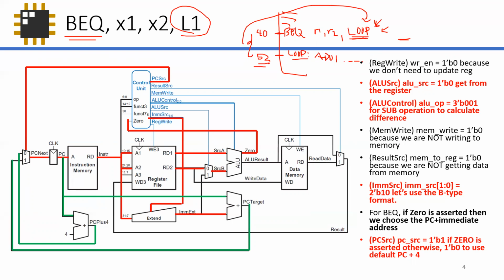So we don't really specify the immediate. But the one you're pertaining to is that, unlike for store word instructions, SW x0, you specify the immediate, 12, and then x0 or whatever register you're trying to put in here. So yes, it is in multiples of 4. Or rather, it's from the software designer's perspective that I have to put it in multiples of 4. Now, in some cases, it may not be in multiples of 4, because you actually have instructions that are load half words.